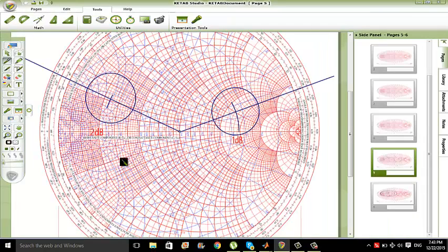And now for the circuit to be matched at the maximum power gain, we choose the path from the constant gain circle at the load. Now we move clockwise on the red circle like this, and then move a little bit on the red circle to reach the blue circle, and now we move clockwise on the blue circle, which means that we will add a series inductor and a parallel capacitor.